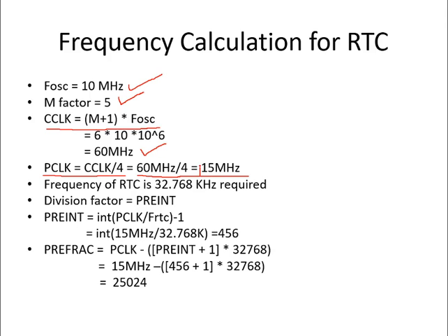Okay, so this is important. Now we require the frequency for RTC as 32.768 kilohertz. Here comes the prescaler integer and prescaler fractional part.